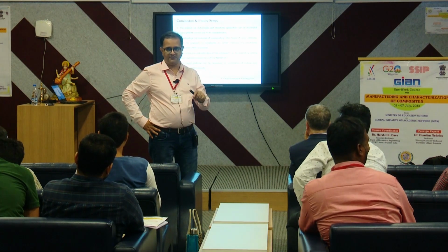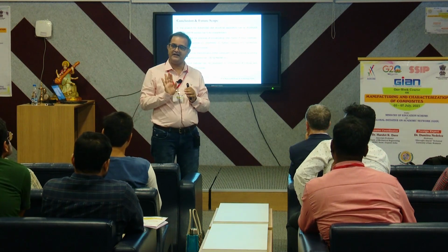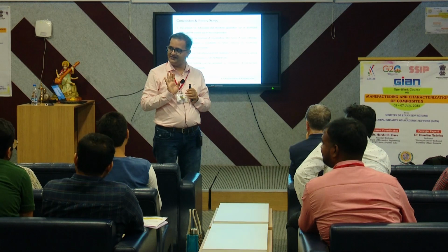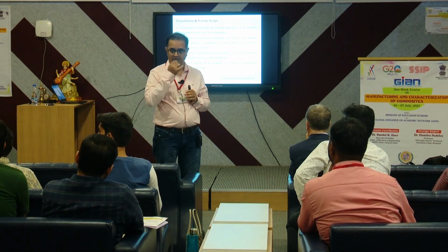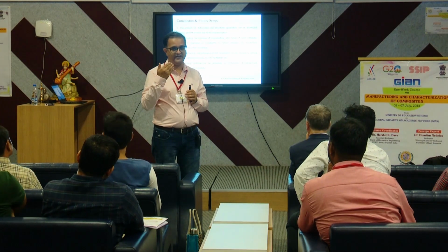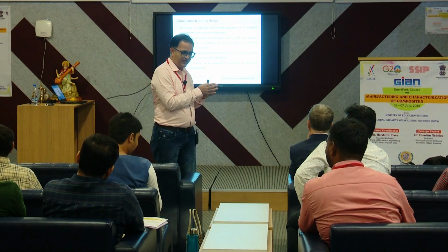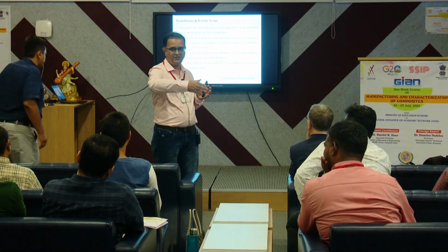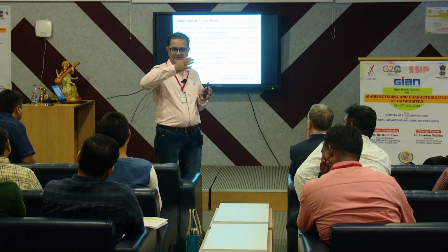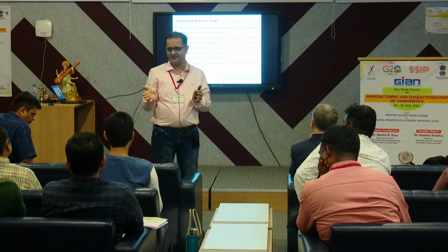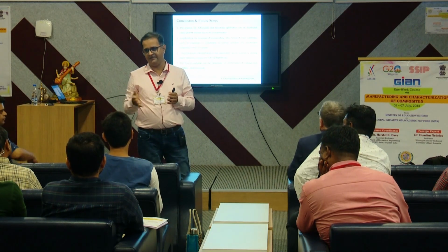Now, when you infuse something, those particles may get entrapped in the fiber and may also restrict the easy movement of the resin. So, the way it would behave, whether it restricts the flow, whether it concentrates the powder at one particular position or allows it to flow, and under those different situations how that part would behave, that is an interesting study.